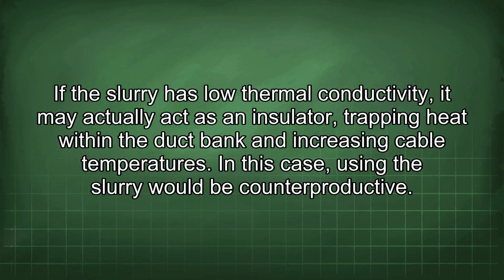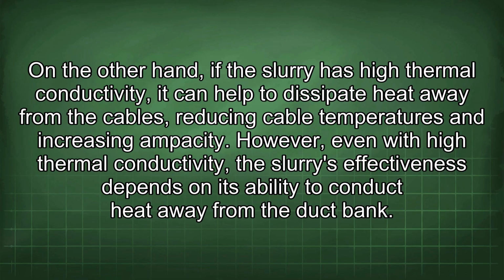In this case, using the slurry would be counterproductive. On the other hand, if the slurry has high thermal conductivity, it can help to dissipate heat away from the cables, reducing cable temperatures and increasing ampacity. However, even with high thermal conductivity, the slurry's effectiveness depends on its ability to conduct heat away from the duct